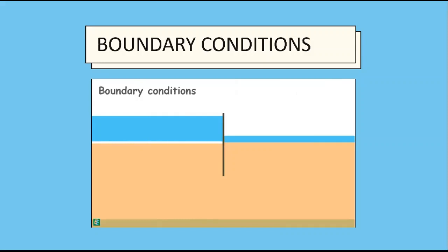And if we notice, it is the first equipotential line of our flow net because at every point on this line, the total head is the same. The second boundary condition is similar, and that is the downstream surface. It is the last equipotential line of our flow net.